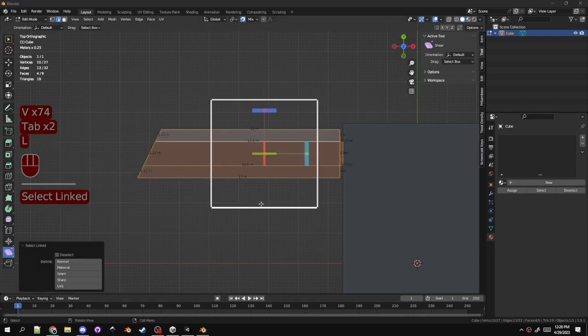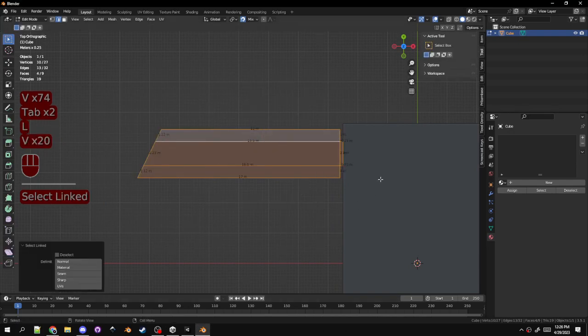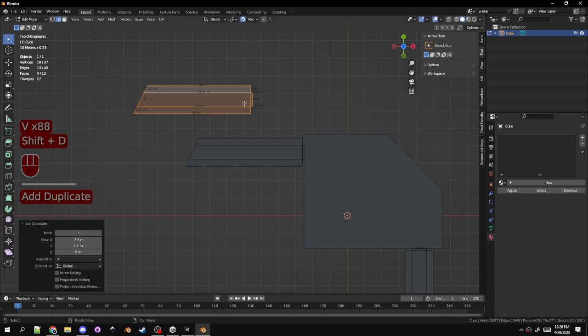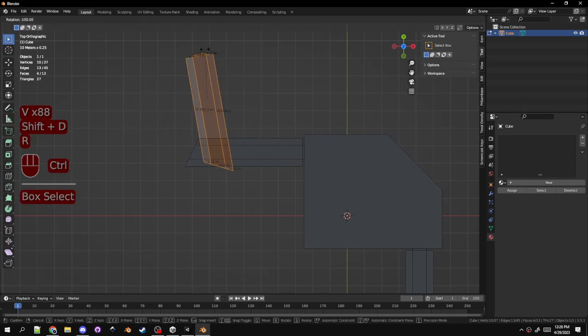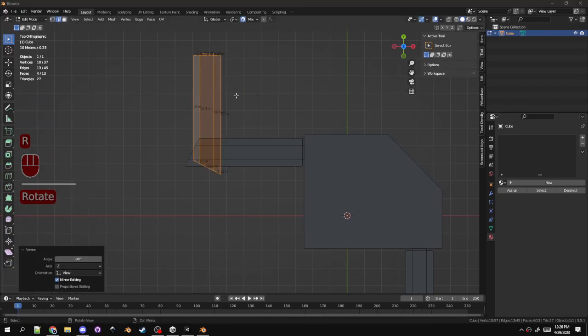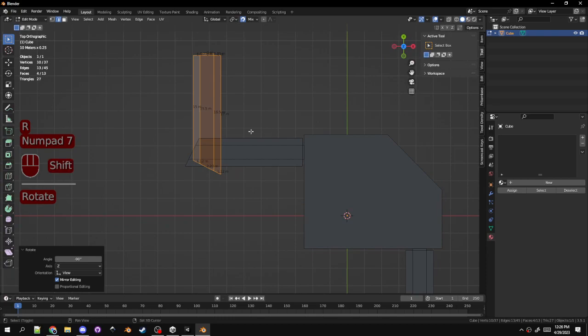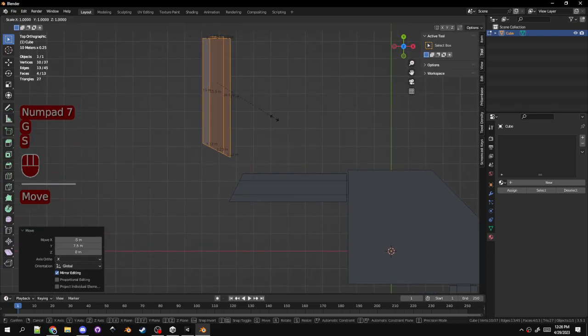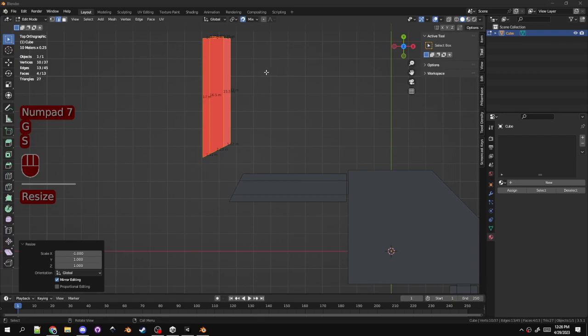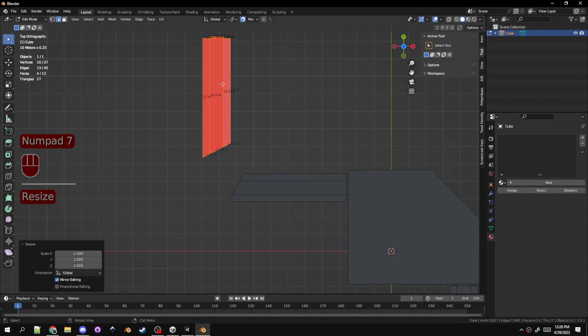I'm going to select this shape using L. L selects just linked shapes. These aren't connected with vertices, so they're not being selected. Duplicate with Shift D. Or rotate it. Right. So I scale it on the x-axis by -1, so it flips over. And you can only see if it's red if you have